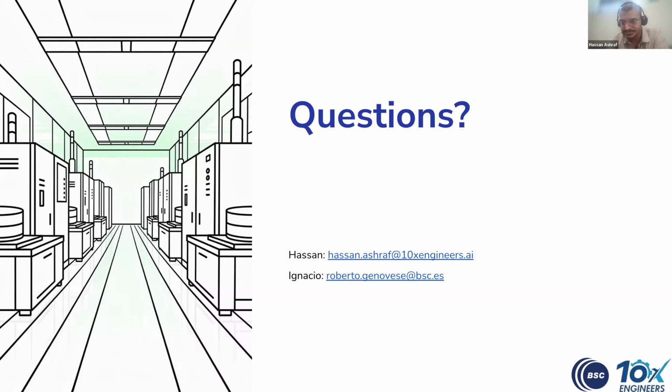Yep, definitely. So, Emmanuel said, I don't exactly understand the relationship between Cocotb and UVM. What I understood is that UVM is a set of methodologies for building test benches, so it should be unrelated to the language we use to implement our test bench. So yes, UVM is a standard methodology that comes with an implementation in SystemVerilog.